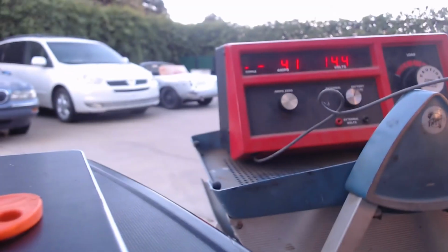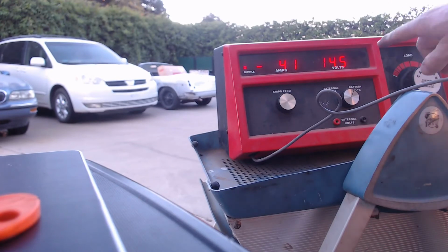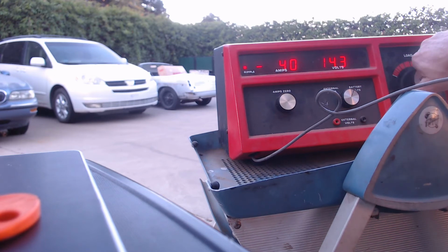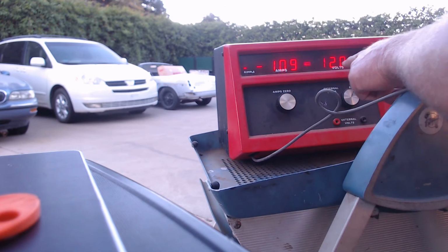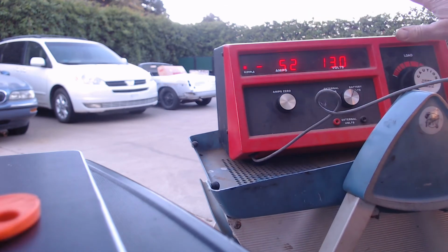We can see that this thing's charging at 14.5 volts, and it's at about 40 amps already, and the reason is because we got the headlights back on again. I'm going to go ahead and crank this up and get the amperage as high as I can, not letting it go below 12 volts, right about there, about 105 amps, 107 amps at 12 volts, maybe 109. I'm going to let it off there. Okay, so you can see that thing was running right about 109 amps at 14.4 volts on this load tester.